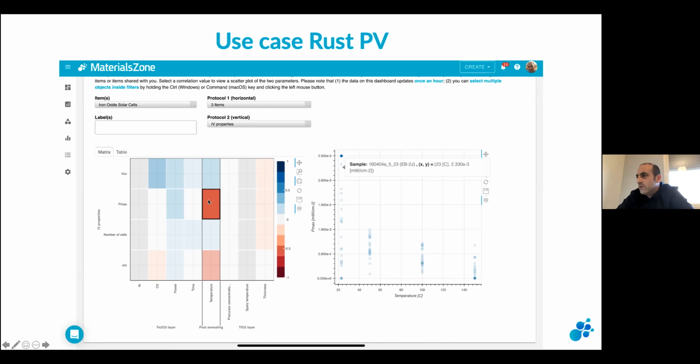And we saw here that the most significant parameter was temperature, and we realized that actually sintering was killing the samples, and this was counterintuitive as a scientist, because typically you will struggle to create pure crystals and you would sinter, and apparently sintering cracked the samples and created shortcuts, and was a lot of damage.